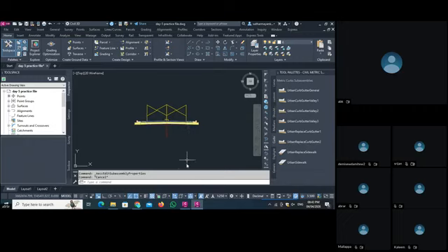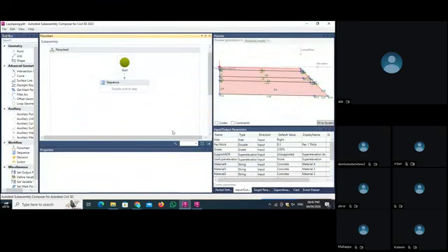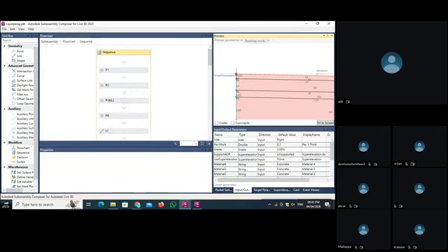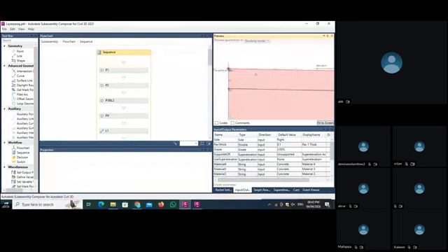I will show you one thing here in the sub-assembly composer. See, when you create this sub-assembly composer, there is a point first. If I am talking about this one lane only, the first layer, you can see here the points P1, P3, and the points P2, P4, and P5. So the first one is the point. So you saw three things in that properties: point, link, and shape.